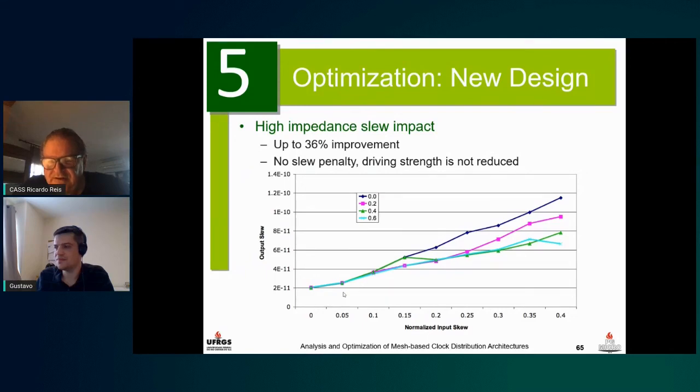How much is temperature gradients? I don't know. I think it varies a lot from the assumptions made in the characterization of the clock network. So I'm sorry, I don't have any data that I can quote. The only thing that I do remember from my experience analyzing scenarios was that the power supply noise was probably the biggest source of variability in the clock delay.